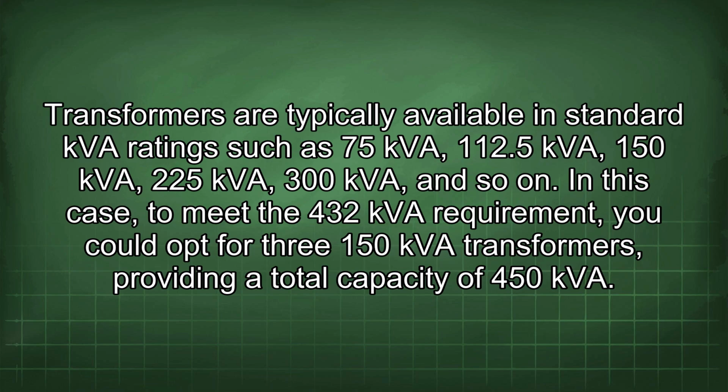Transformers are typically available in standard kVA ratings such as 75 kVA, 112.5 kVA, 150 kVA, 225 kVA, 300 kVA, and so on. In this case, to meet the 432 kVA requirement, you could opt for three 150 kVA transformers, providing a total capacity of 450 kVA.